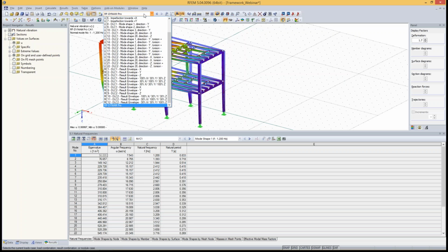And now we see that, first of all, you always know where the load cases are coming from. So there's always a note inside. This is the load case 8 is coming from dynamic load case 1 from the mode shape 1 in the direction 1. So it's always clear. The origin is always clear. And now in case of the dynamic load case 2, we have 2 load cases for mode shape 1 in the direction Y. So you get 2 load cases for each mode shape. One is in the torsion plus direction and the other one is in the torsion minus direction.